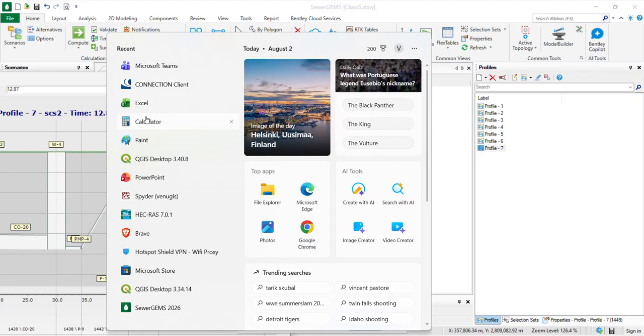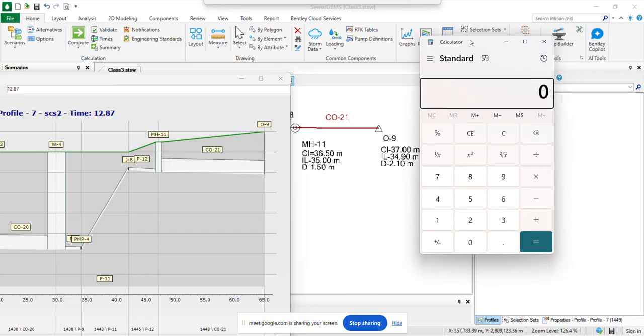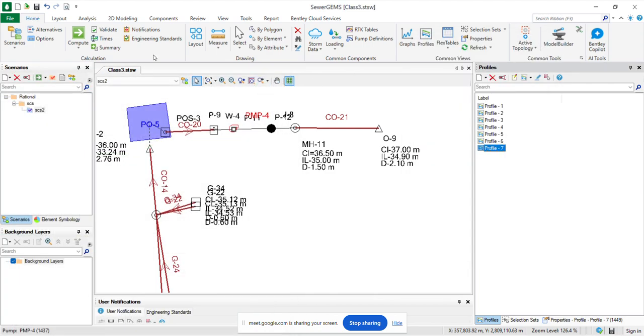This is a simple calculation for the head. What I'm making is 35 minus 31.2, the difference between this point and this point. I'm going to connect it a little bit above, which is 700 mm diameter. So I'm adding 0.7, making 4.5 as the head for us.